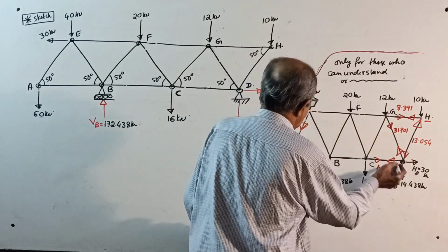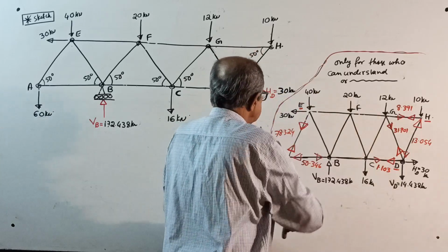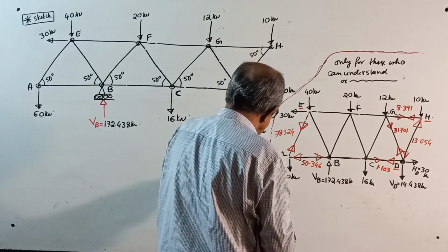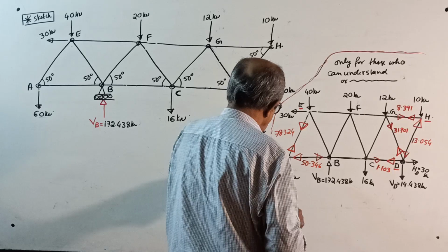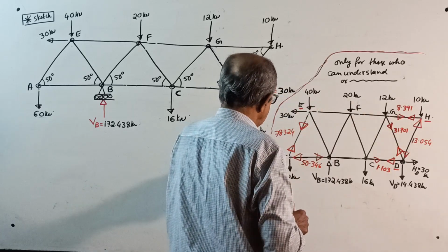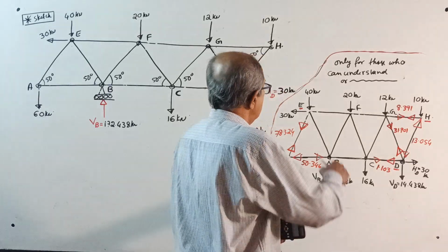Okay, now I will go to joint C. Now whichever joint D is over, I will go to joint E. Down 78.324 into sin 50 is some vertical down component. Another 40 is there, plus 40. So net unbalance now is 99.9, that is 100 kilonewton, acting down.